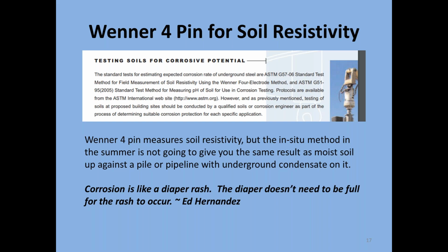Because that's very important for the electrical engineers to know, because if in the summer the soil is very, very dry, then that's going to be a very huge electrical resistance, and they need to know that so that they can design that electrical grounding system appropriately. See, so that's the main purpose of 1 or 4-pin.